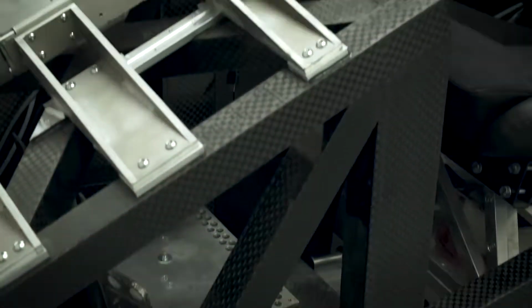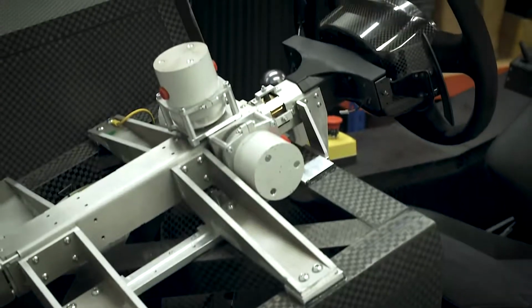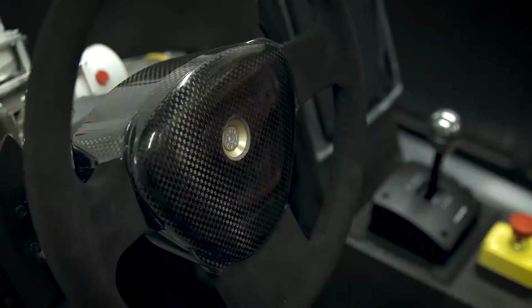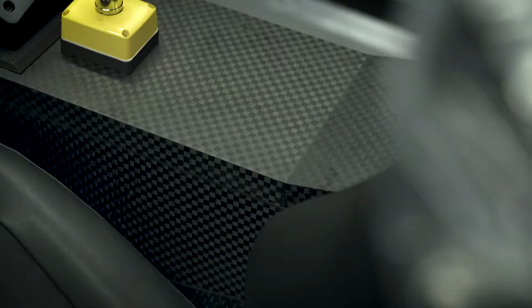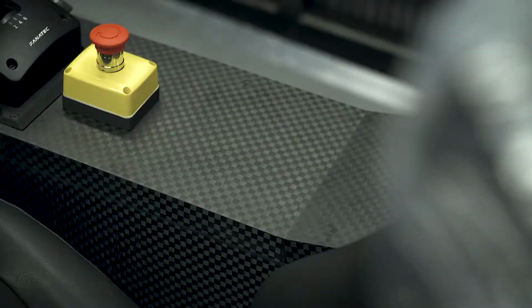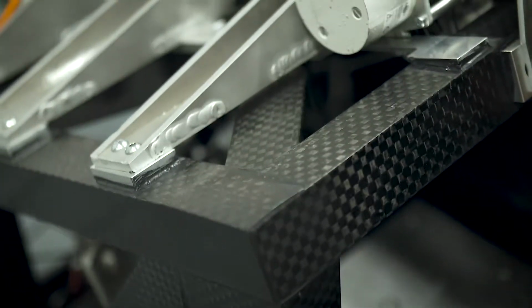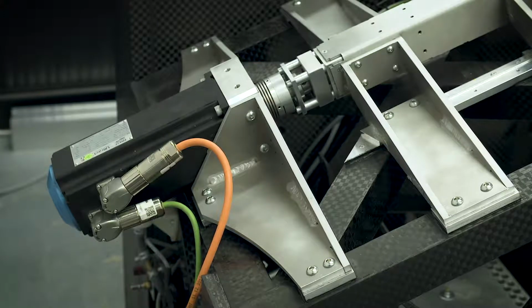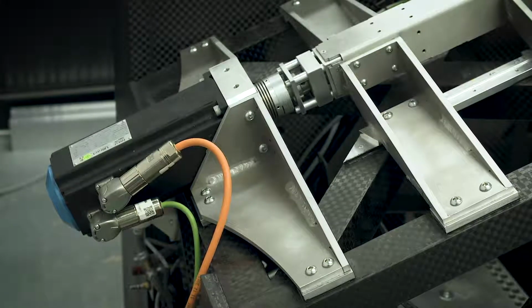You can see that carbon fiber is used extensively in the construction of the compact NVH simulator. The entire frame and even the steering wheel are composed of carbon fiber. This makes an incredibly stiff structure suitable for delivering controlled, accurate vibration to the evaluator. No modes of vibration of the frame or steering wheel significantly affect the vibration response, enabling accurate vibration and experience.